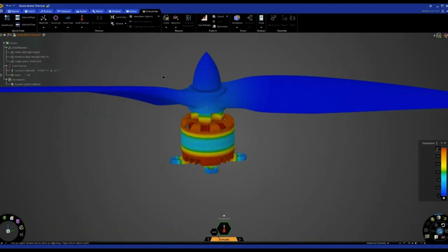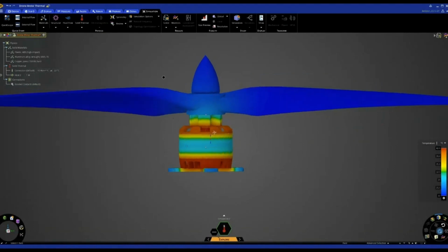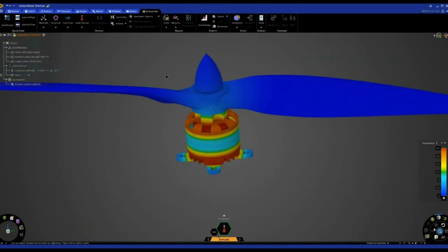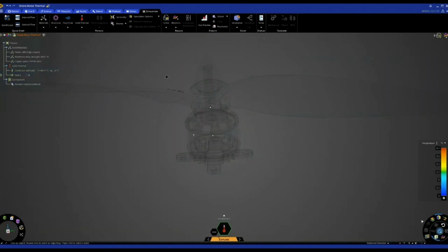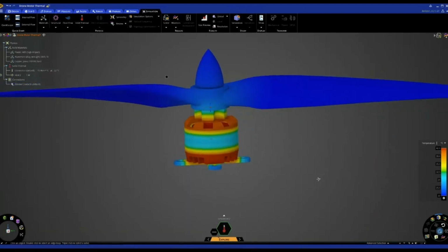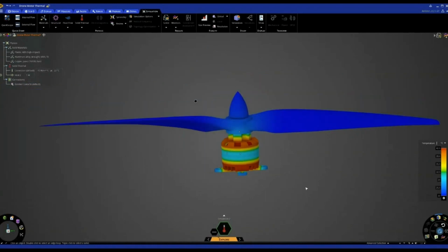We can see we hit a max temperature of 42 degrees here. We can see the temperature variations within the parts. We can section our model if we need to and get inside and pull calculations off like we've seen in other simulations. But another cool feature of Discovery is the ability to run parameter studies. This works in fluid and structures as well.